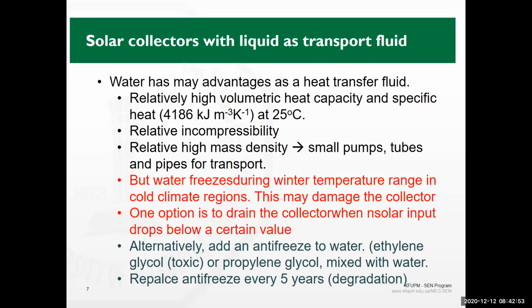I've seen it in different designs, doing the water heating and then passing a heat exchanger by the water to heat the air, and then air would be used for heating. So both would be there. Water heating is more common. Water has many advantages. This is why it's more common, because it has a higher specific heat. So you can easily transfer energy in water, hot water or even cold water, more than air.